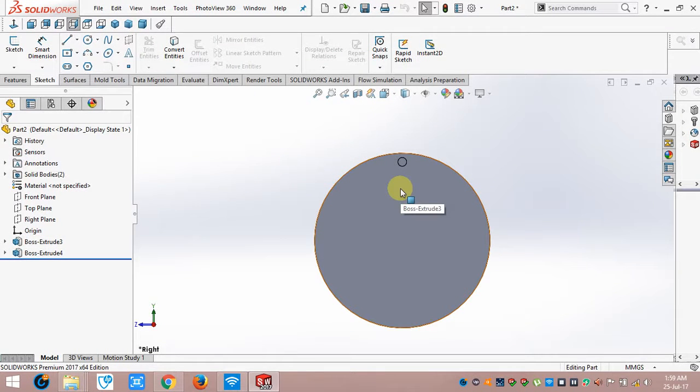have a predefined direction, because as we had seen, in a rectangular system we had the z and y directions predetermined, because we could define the axis by taking the edges of the element or the base plate. But here it's basically a circular system, and for making a linear pattern we can't actually apply a circular direction, because it's not going to make a pattern in a circular path. So what I'm going to do, I have to